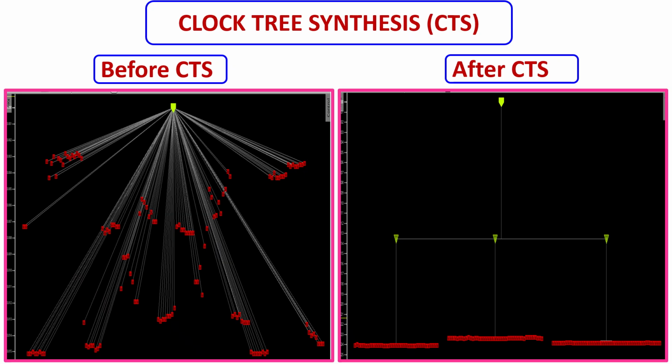The next is clock tree synthesis, balancing time across millions of flip-flops. Imagine 5 million flip-flops in a chip. All must receive the clock signal at almost the same time. If they are not receiving it, setup and hold violations occur and the chip fails. That balancing act is done using clock tree synthesis.